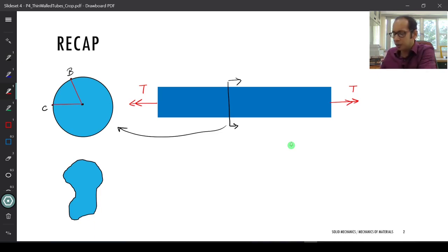What we have learned is that since each of these points are at the same distance r from the center, my tau, that is the shear stress at B, must be equal to my tau at C, 2 points at the extreme periphery, right? Now this is true because your r at B is equal to the r at C, which is equal to the radius of the circle.